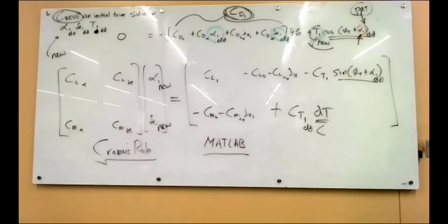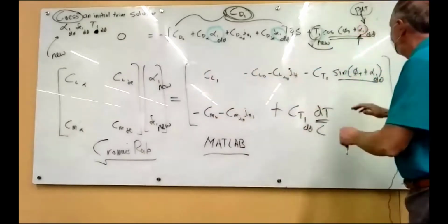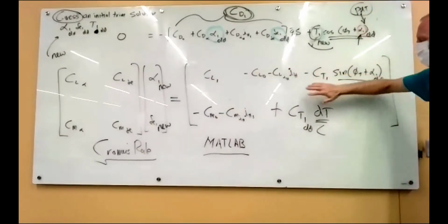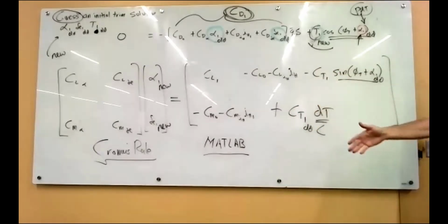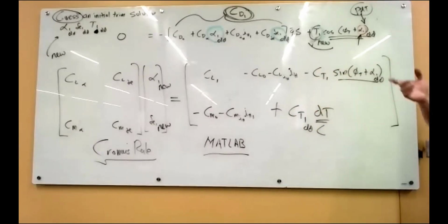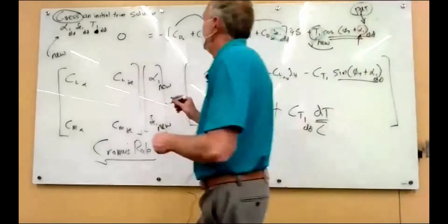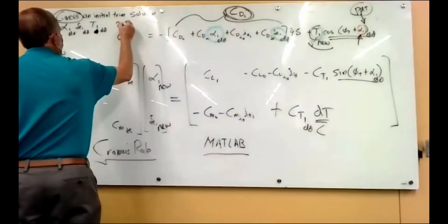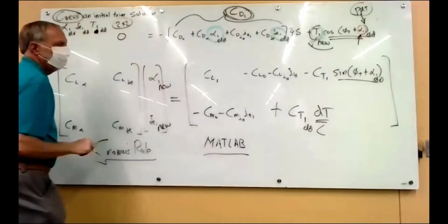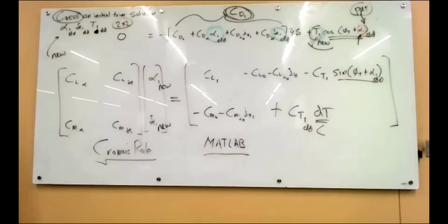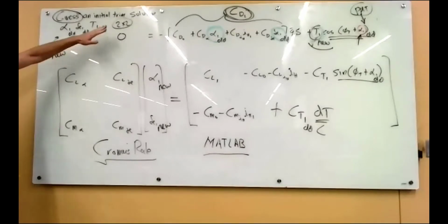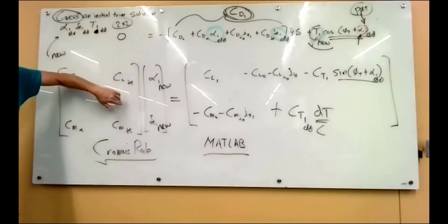How about that trim solution you did in the previous homework? So you can solve this approximately, right? The trim solution where we knock this out and knock this out, and you can get a pretty good estimate. You saw it wasn't bad. And then that's your initial guess, from the 2 by 2, and the thrust you get from that. And in fact, in the homework, you're going to do this. You're going to go for that same airplane, you're going to go back and get your solution from homework number 4. That's going to be the initial guess. And then you're going to write the short bit of code in MATLAB to do this.